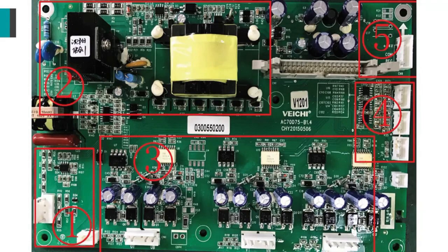For the small power inverter, just now we know that the power board integrates IGBT, relay, and rectifier and pre-charge circuit in one board. But for the big power drive, like 110 kilowatt, as I just introduced, it has lots of power boards. The main circuit power board, 24 volt power board, IGBT power board, IGBT drive board, and so on. So it is very complex for you to repair it. You just need to know how to check it.